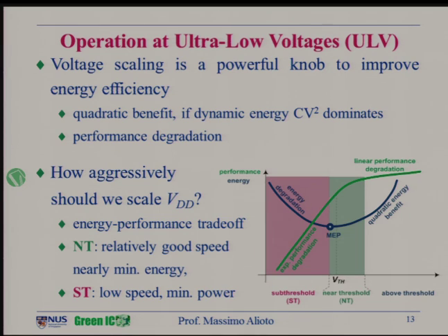So, duty cycle blocks. Instead, in subthreshold, we basically have low speed, very low speed here. And energy might not even be minimum if we push aggressively on the voltage, but we certainly can have minimum power. So that's the right spot for always-on blocks.